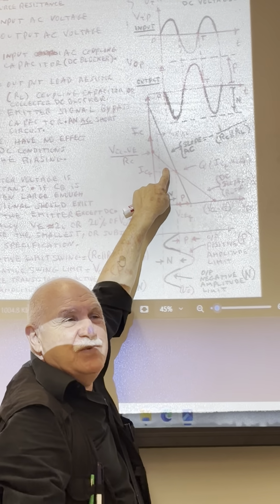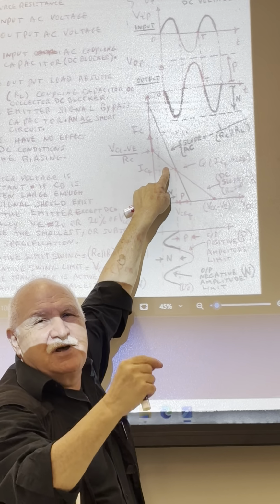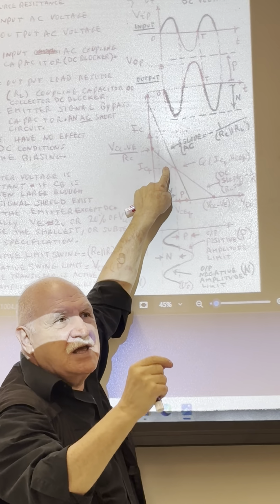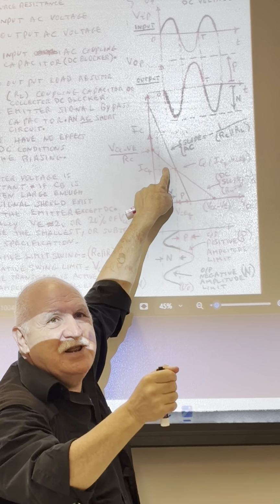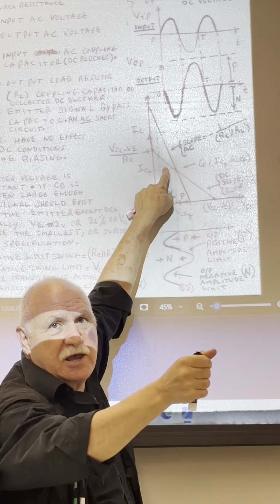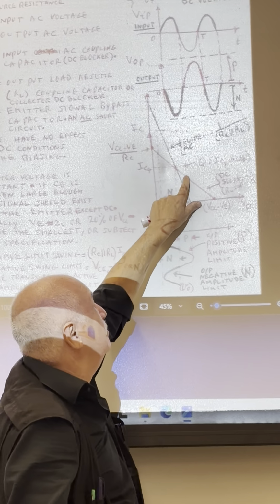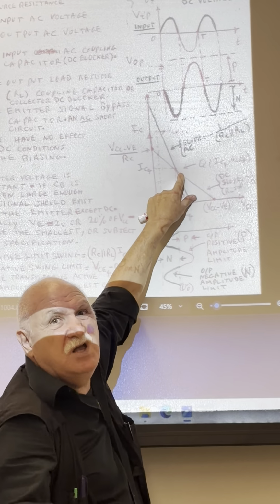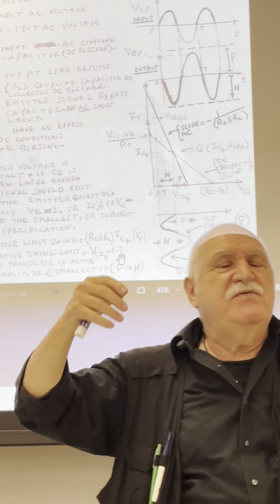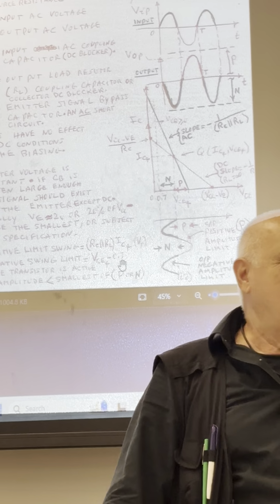So remember in the beginning when you started putting the operating point in the middle of the DC load line? It's just like spoon feeding you in the beginning, giving you soft stuff to eat until you can chew the real steak. It's just to tell you, look, it's easy. If there's only one DC load line, yes, you put it only there. But making an amplifier with an RC and not having a load, what's the point of it? You've got to have a load.